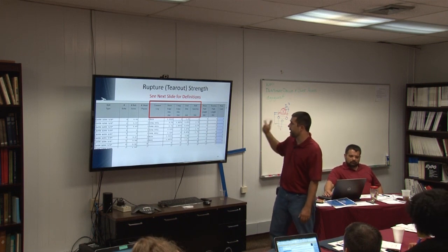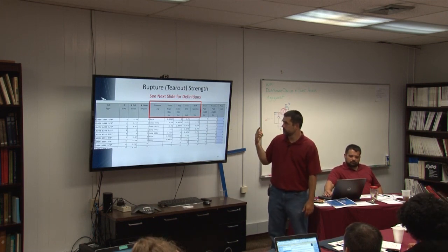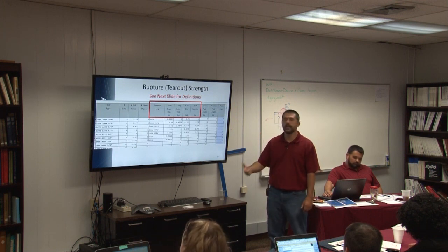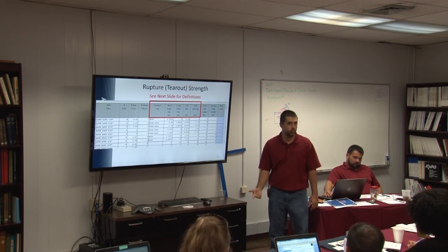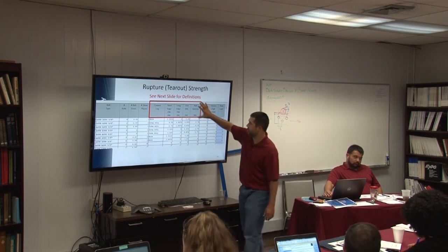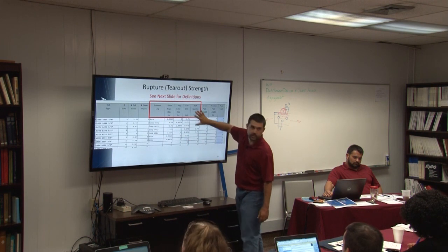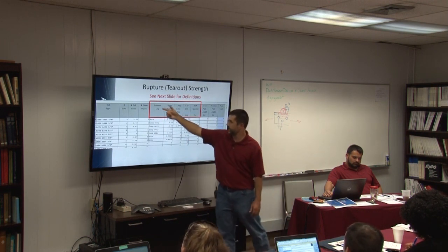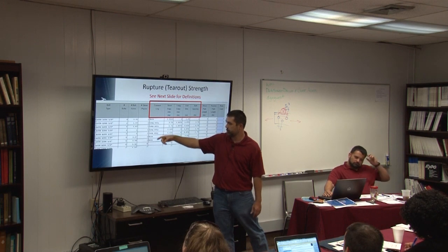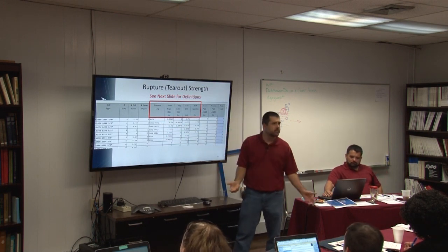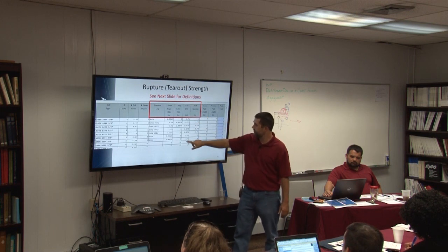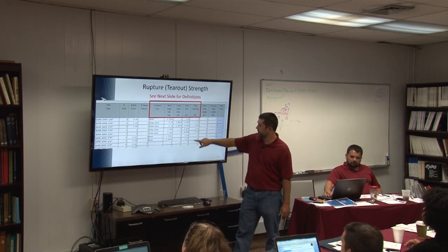Okay. This is what I would say is the one piece of tower modeling that's most omitted because it takes the most time to do. And it is basically filling out all of this information. We're talking about the connected leg. It could be the long leg, the short leg, both legs. Most of the time that's input. But then we've got the end distance, the E value, the bolt spacing,